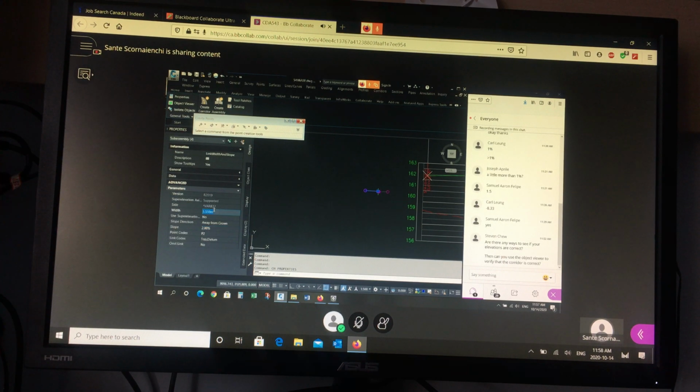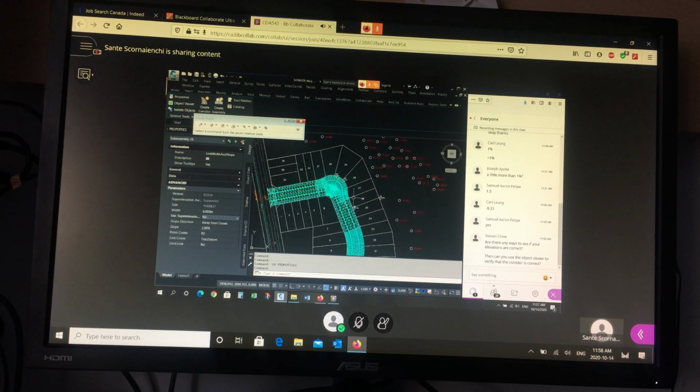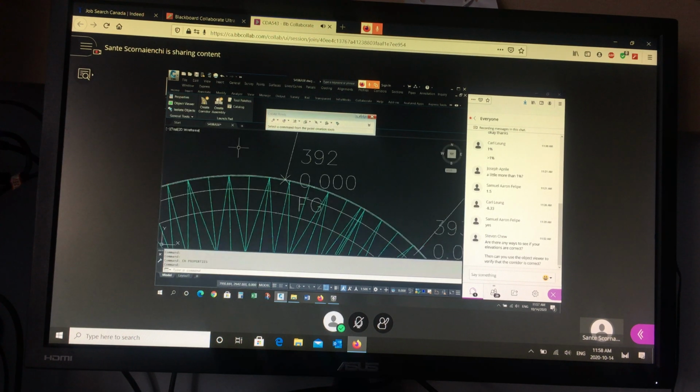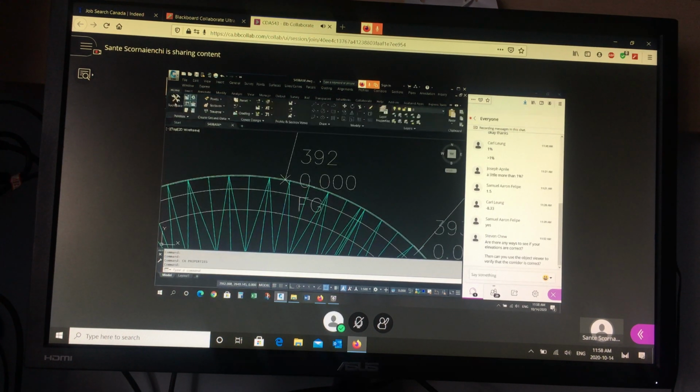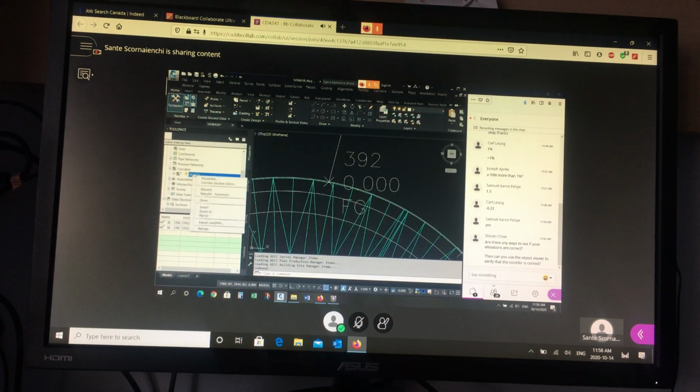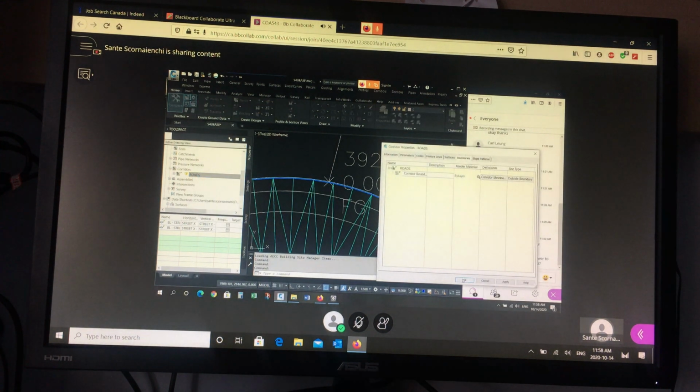Well, instead of going right to the edge, I'm going to make it a little bit longer. So in this case here, instead of 5.55, I'm going to make it 6 wide. And when you widen the boulevards, you extend the lot a little bit, and this is what happens. So if you go back to your corridor now, your corridor is upset, right, because you made a change. So I'm going to right-click, I'm going to rebuild. Watch what happens. It's going to get fatter. It's going to expand into the lot. Whoops. Sorry, I'm just going to rebuild.